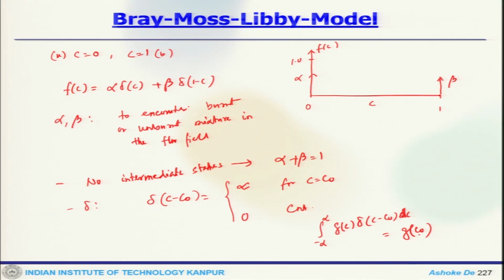So, this is how you define it, but one thing here, this probability distribution function, the definition here is that these functions are a priori assumed or presumed. That is why this flamelet kind of approach is also known as presumed PDF approach.